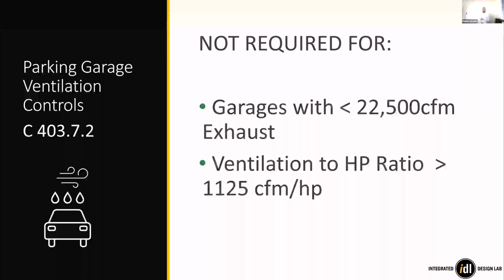We have these controls in the basement in our parking garage down below. So if the fans randomly turn on and the damper's open and you hear this huge whoosh, which terrifies me in the middle of the night sometimes when I'm walking home, it's because they're on a timer that operates every so often, or one of the carbon monoxide sensors. So those controls are required according to the energy code. Otherwise, the mechanical code is concerned with just having those fans in there. It doesn't care when you shut them off, and from an energy standpoint, it matters a lot.